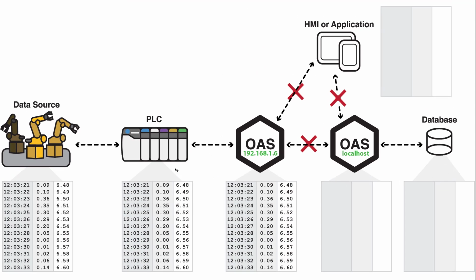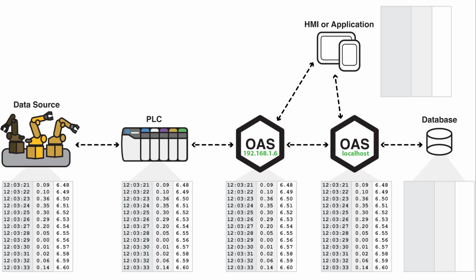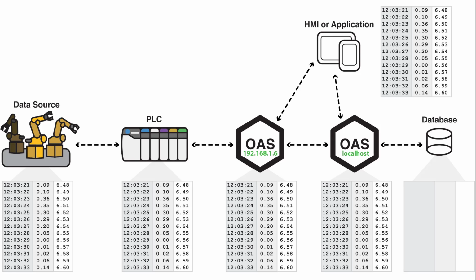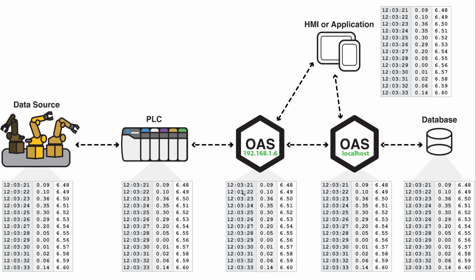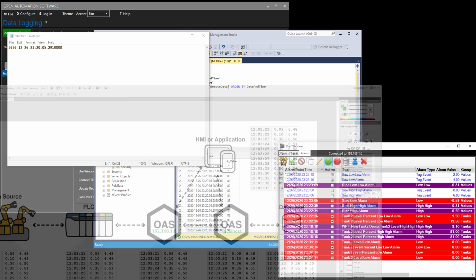So if we look back at our diagram, we have now resolved the issue with the HMI interface connection, and we've also been able to resolve the connection to the database engine, the data logging engine that's doing the recording. So that data would then be able to be delivered both to the local database data logging processing engine and also to the operator interface. All of the data has been passed forward from the Raspberry Pi device during that temporary network failure.